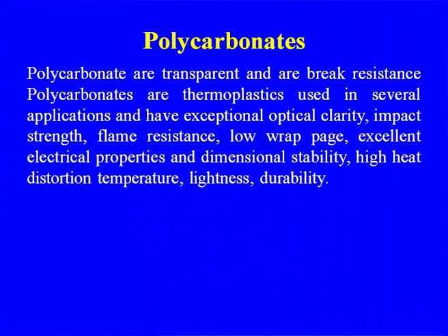Polycarbonates are thermoplastics used in several applications and have exceptional optical clarity, which is why we use them in optical glasses. Impact strength, flame resistance, low warpage, excellent electrical properties and dimensional stability, high heat distortion temperature, lightness, durability. These are some of the important properties of polycarbonate, which have led to more and more use of it.